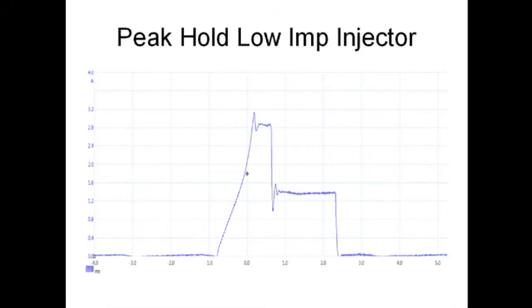We basically have two different types of injectors in our business. We have low impedance and high impedance in the gasoline injection arena. So this would be a saturated injector that normally has a resistance value of 12 to 16 ohms, figuring a nominal voltage of 13 volts. We should see somewhere between 3/4 and 1 amp draw on that, but they should all have the same amount of current flow and especially the same injector offset. That is, we're going to measure the opening time of the offset.